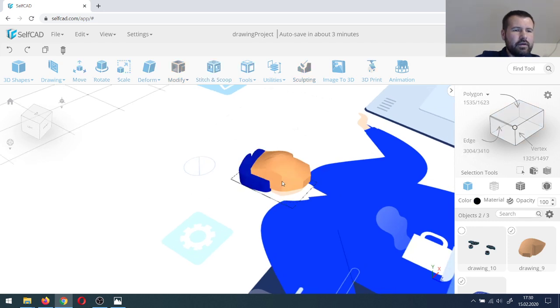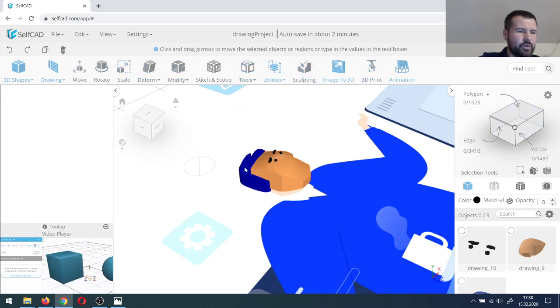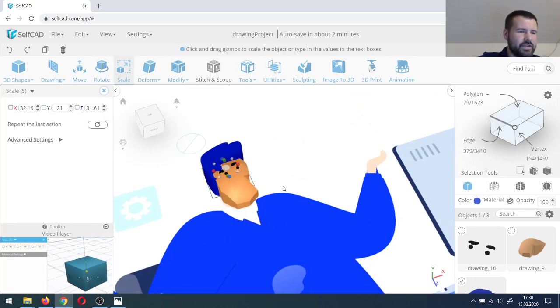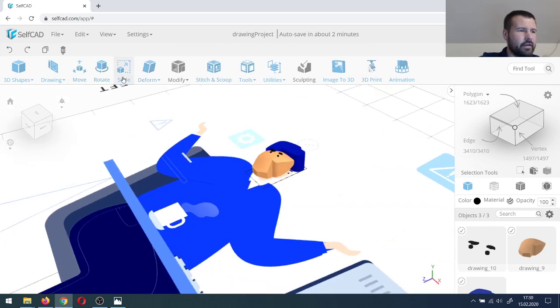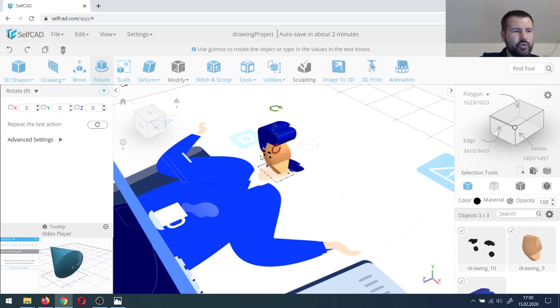So the last step for this would be rotating it. I will just show the rotating process on those few elements that we have here. Let me just position this more or less correctly. If you select everything and rotate, in this case we need to go under the 0 value and rotate 270 degrees.